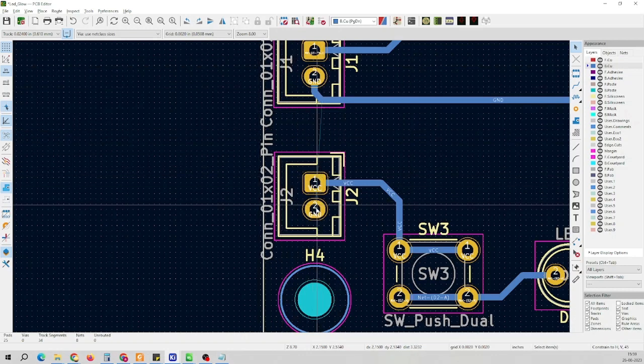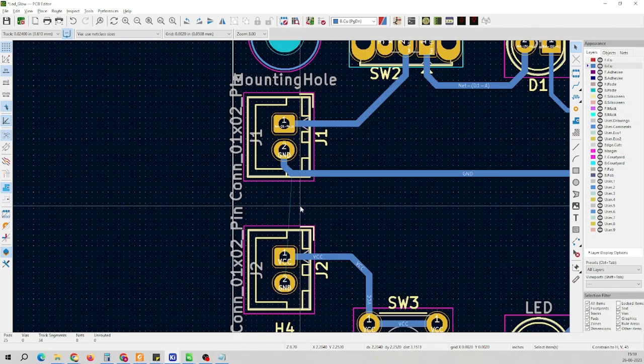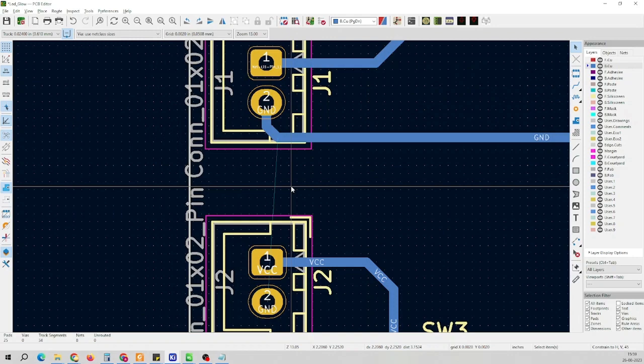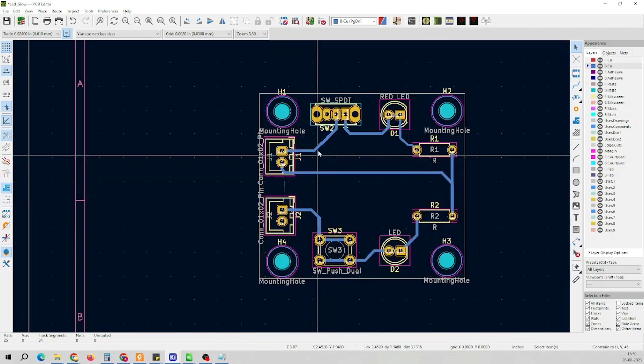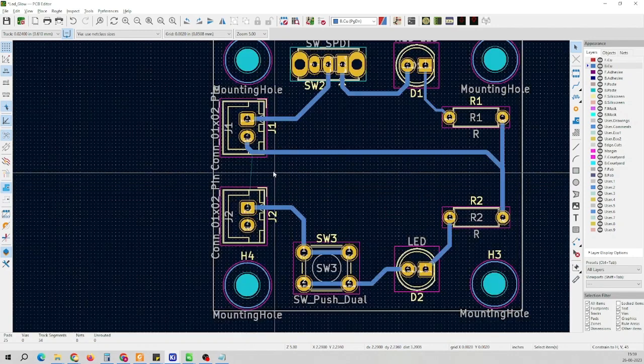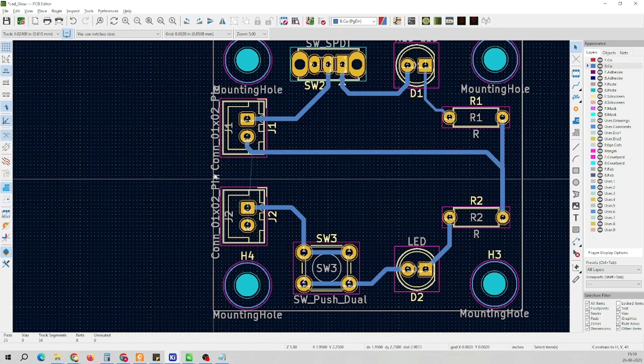So now as you can see, this wire is not connected, but I have to connect it somehow to this line. One way is to move it from this point to this point, but the issue is that there might be some concern with respect to the nearness of the track to the edge.